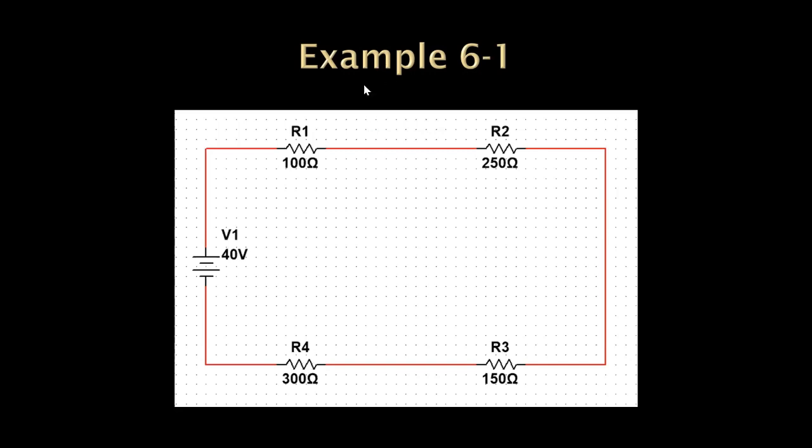Okay, and power. So in a series circuit, my currents are all going to be the same, and P equals I times E. So if I is the same everywhere, now my powers are determined by my voltage drops. So if I'm going to have 3 times the voltage drop at R4, I'm going to have 3 times the power at R4 than I had at R1.